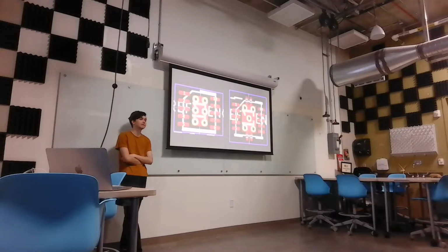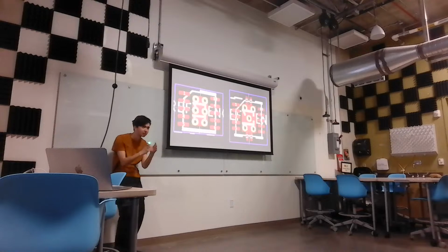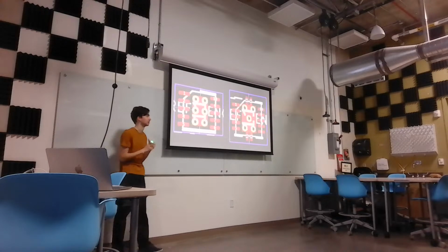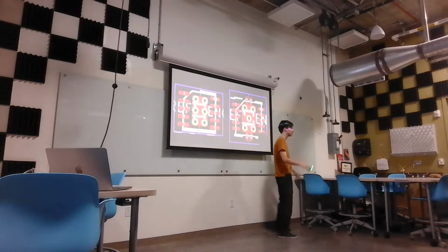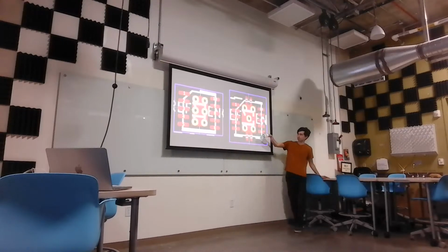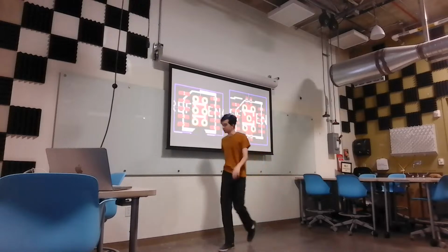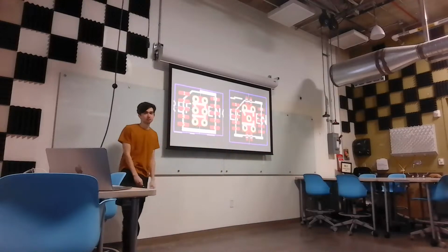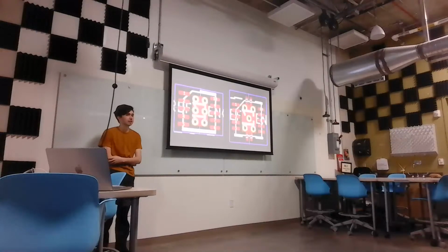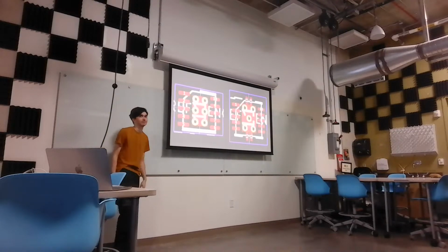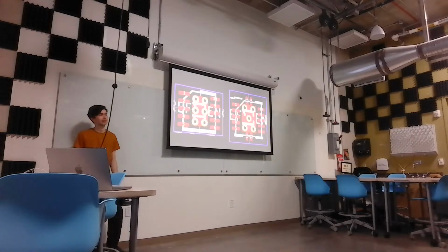First problem: I used the wrong footprint for the main part of the chip, the most important chip. They look pretty similar, they're not. I don't know how that chip ever turned on, because clearly these pads don't line up. So I eventually realized that this footprint thing was causing a problem in that video. And eventually I was like, okay, screw this chip, screw this whole thing.